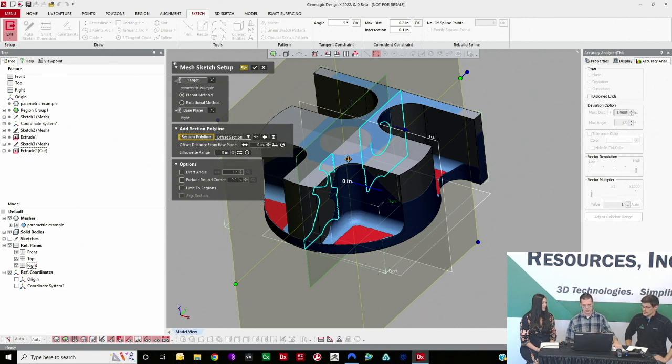And that was on my list of things to talk about as well. What you can do is you can copy a scan. Like, let's say a modeling operation that I was going to perform would require me to delete some of the actual scan data away. What you would want to do before you actually delete that scan data is make a copy of the scan and perform those direct scan data modifications to that copy. That way you're not destroying any of the original scan.